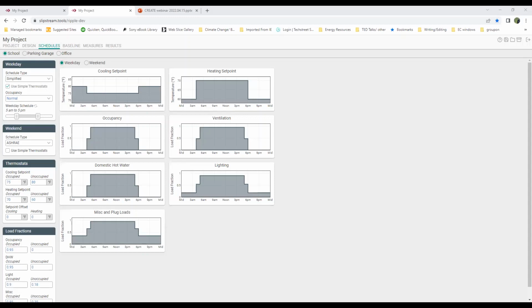Yeah, that's a great question. Unfortunately, we don't have any built-in technical process to adjust for those degradations. That would have to be a manual adjustment. And a lot of the times we have not put in those values because that's going to be a little bit more specific to the vintage of the building and the kind of degradation we're talking about, right? So the tool does not automate that process, but that's absolutely something that has to be accounted for when we're talking about existing buildings that are, say, over 20 years old.